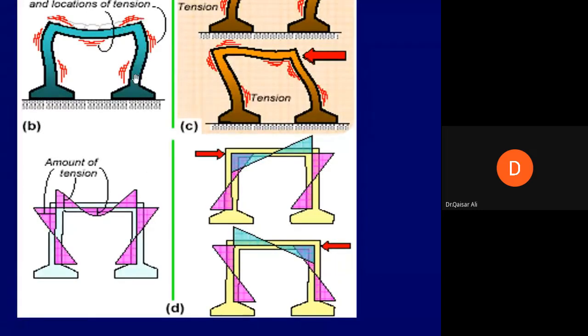Okay, coming to the lower part of the beam. If you look at this lower part of the beam at the same location on the right, there is no tensile stress coming from the gravity load. And normally we do not place any reinforcement in this part. By this I mean to say that if you place reinforcement for mid-span positive bending moment, you can curtail some of the bars as you move towards the ends in the bottom side of the beam.